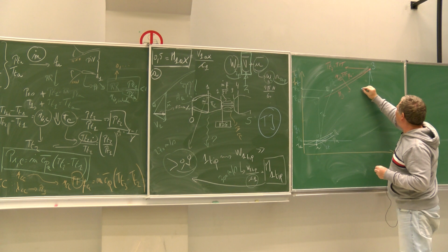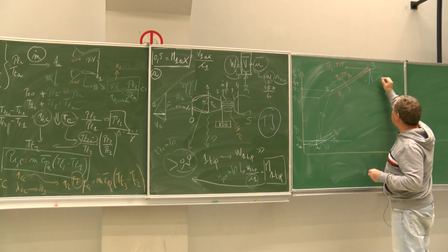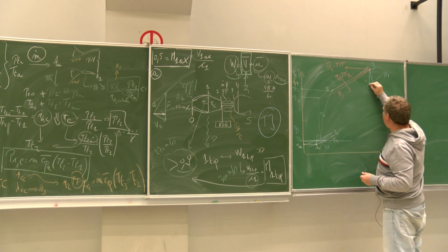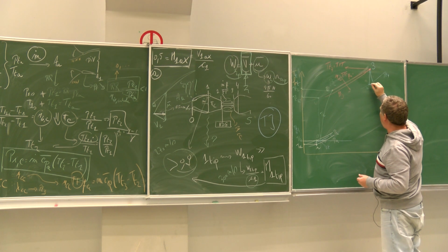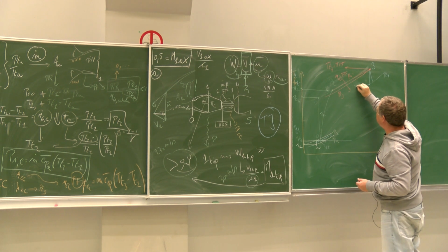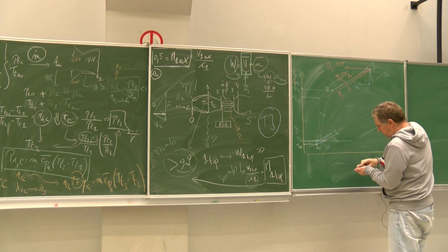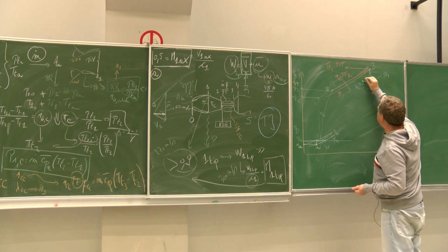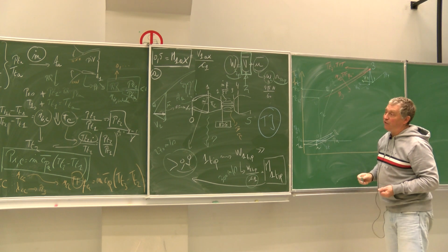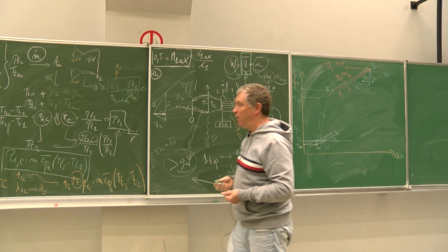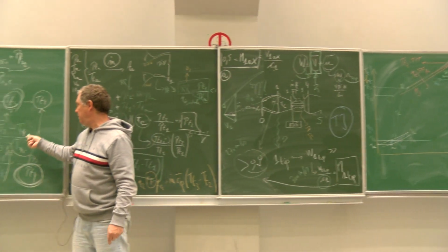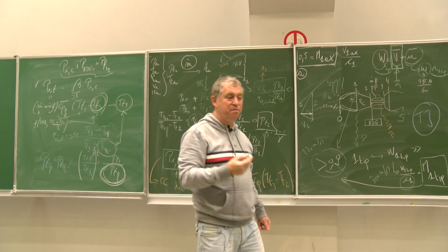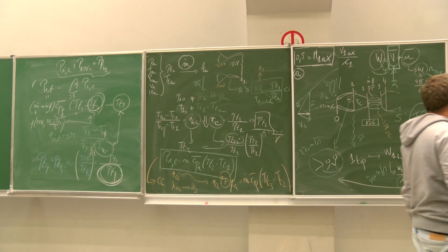So I stop much before, let's say I stop here, with the PT4 that I have computed there, and with here my point 4i, that will fix my TT4i, and here my point 4, that is fixing my TT4 higher than TT4i. TT4 higher than TT4i, so TT3 minus TT4 smaller than TT3 minus TT4i. Okay?